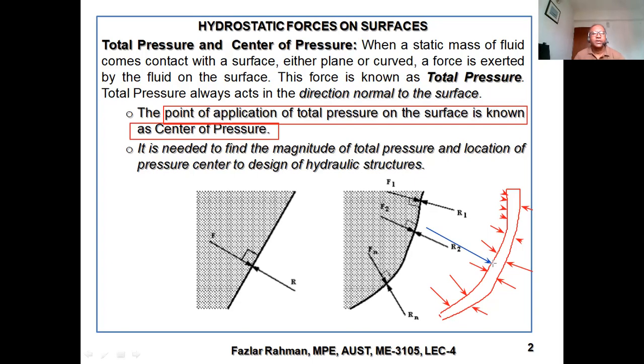It is needed to find the magnitude of total pressure and the location of the pressure center to design a hydraulic structure. Hydraulic structures are those structures submerged under fluid or floating on the fluid. So right over here, it is showing that the resultant force is working through this point, and you can put a reaction right over here.